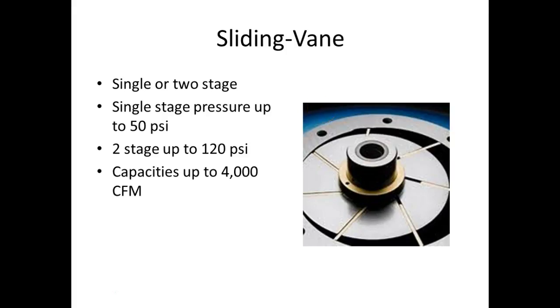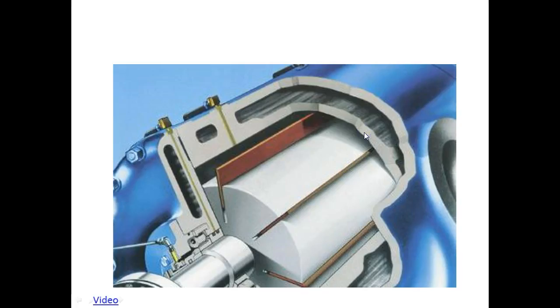right? This is a sliding vane compressor. Can you see how this thing works? Can you see how it decreases the volume? Well, what happens, it's got these vanes in there, and they're all spring-loaded. You can't really see it. And this guy right here turns. It pulls in the pressure inside one of the big gaps, and as it moves around, what does it do automatically? It decreases the volume. If it decreases the volume, what happens to the pressure? Yeah, it's got to go up, right?